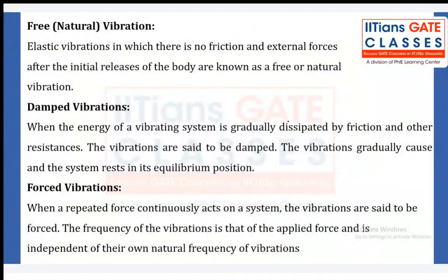Note down the types of vibrations. We have different types of vibration, guys. Free vibrations, that is called natural vibrations. The free vibration basically happens because of the initial disturbances. There is no time varying force present in the system, but we have disturbed the system, and because of the inertia, it is trying to do the oscillations.